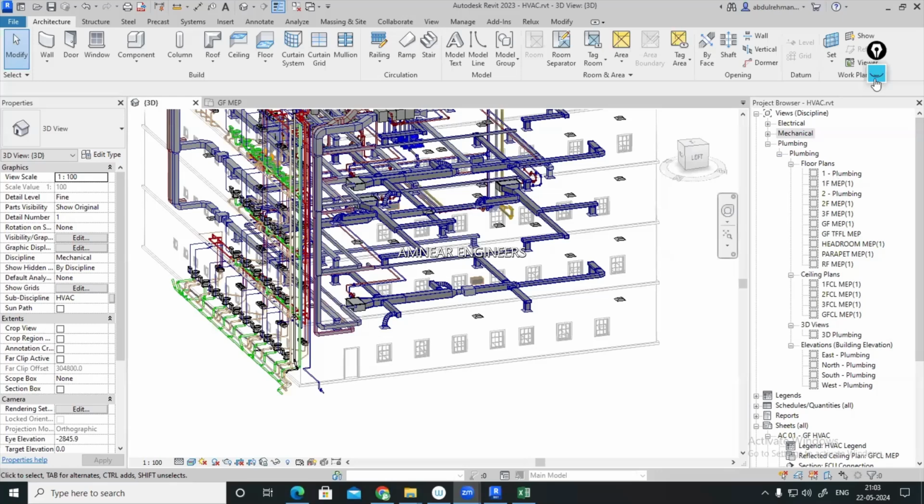So that's why the type of pipe material that we are using will be like schedule 40 steel pipe only, welded joints. Only in which the sprinkler and the 25 mm pipe is joining, there only we will be using the thread. The thread sizes we will be selecting with respect to the K factor of the sprinkler. We have studied that in the design classes. Okay. And so that's why I'm just going to select a sprinkler.